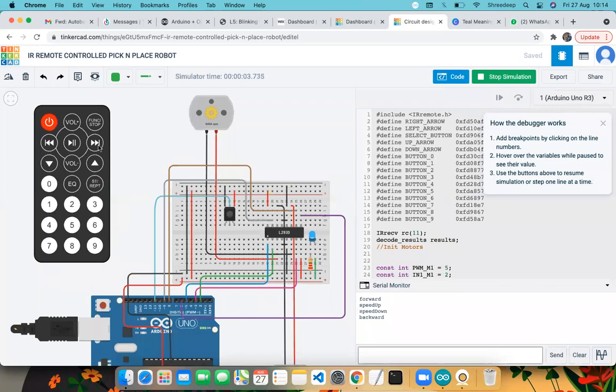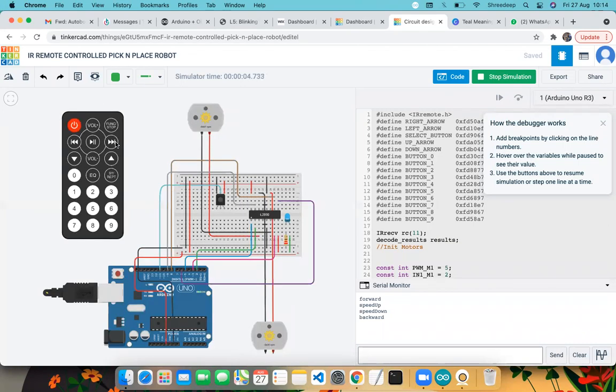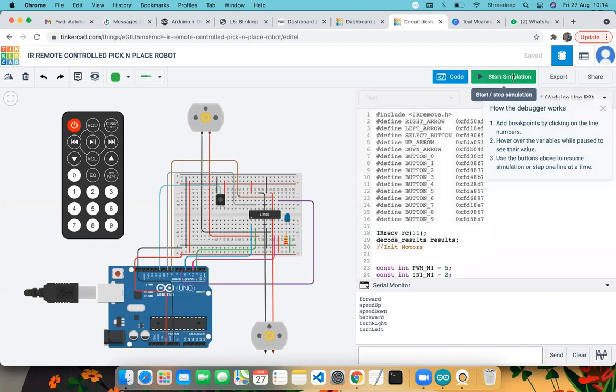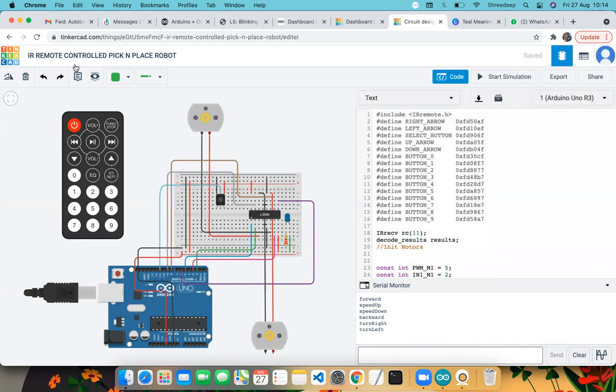Now if you press the right button, you turn the motor in the right direction by putting the left motor on and the right motor off. And if you press this one, that is basically turn left. It is a basically simple model using the L298 or L293 module. What a module is all about is quite simple.